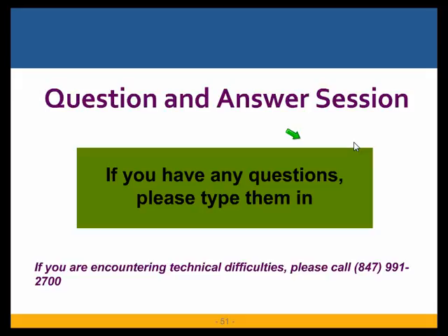So we have three options for tension. We have two options for shear. You need to meet at least one of these. If you meet at least one, you're good, and the program will say that okay, you're okay. So it will consider each of those options and see, okay, option 1 okay, option 2 not okay, option 3 not okay, but option 1 was okay, so your design is good. But if all three options are not okay, then you have to revise your design, you have to do something about it.